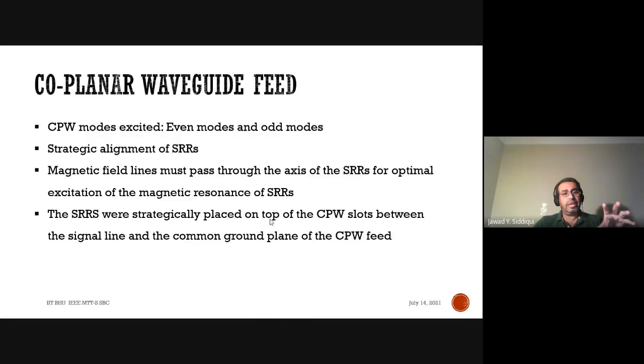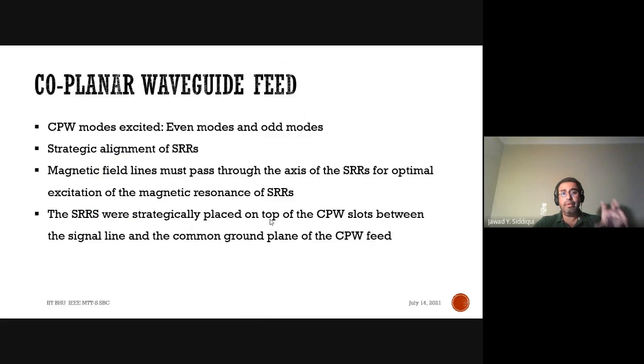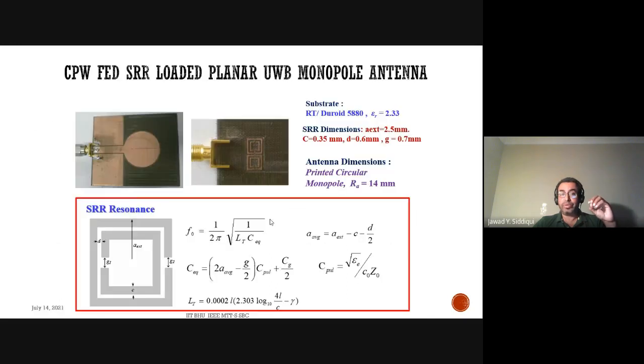So this waveguide, to understand where to place it: the placement of this split-ring resonator becomes very critical, because that is what is going to provide you with the filtering. To give you an idea, you have to understand the coplanar waveguide modes. So what are the modes that are excited in the coplanar waveguide? They are the even modes and the odd modes.